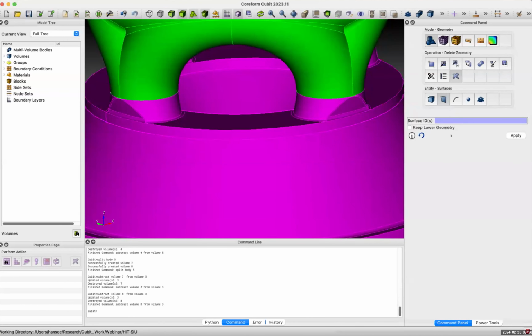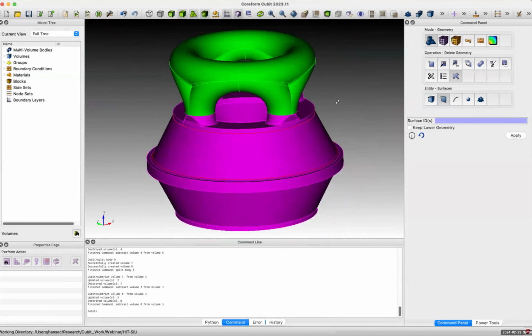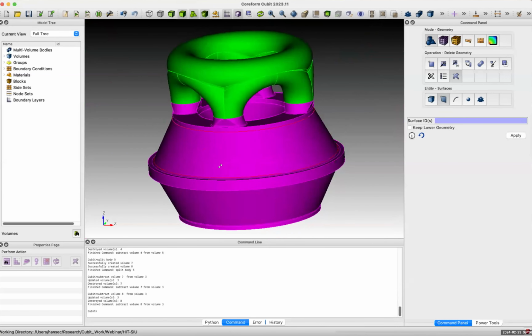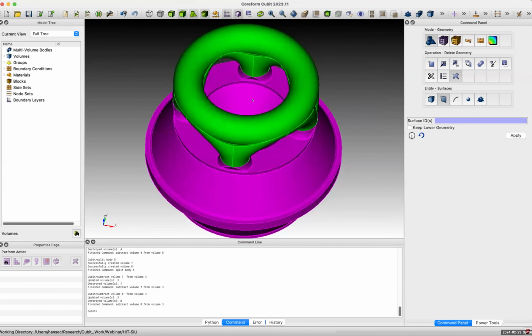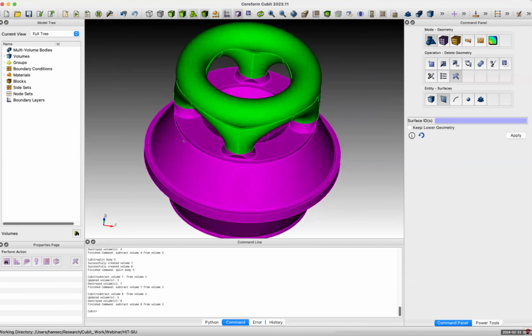All right. And now what I want to do is create these cuts in the geometry so that I have corresponding surfaces in the mesh where I can place my multi-value potential jumps. And so what I need to do is basically create a cut in between each of these connections between the main volume and the manifold.